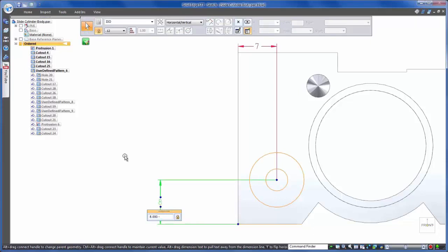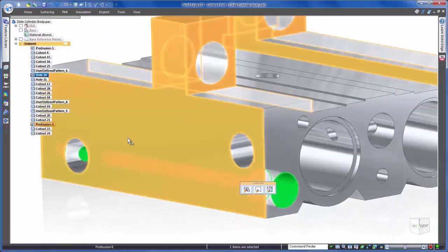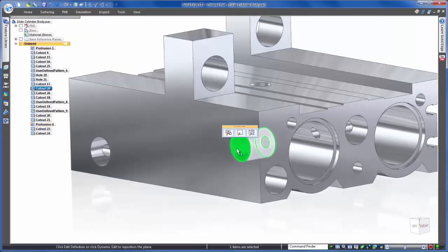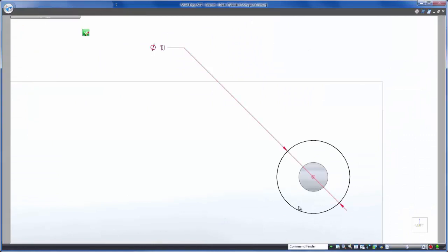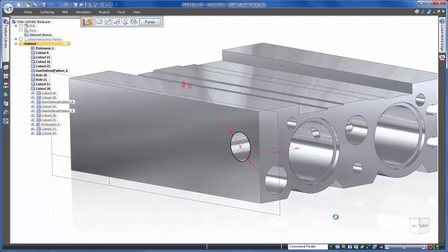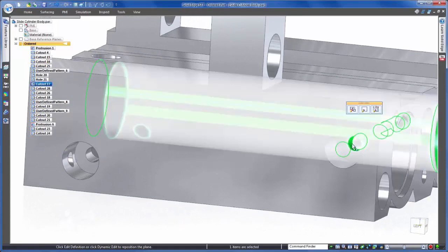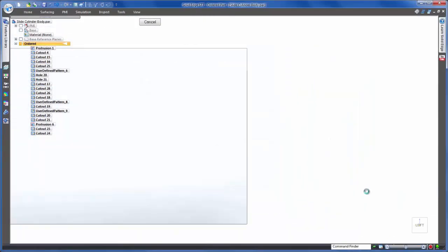Once again, by editing our profile, we can either key in exact values for dimensions or let Solid Edge do the calculation for us. Now that we've subtracted 1 millimeter to the front hole, we need to do the same with the top. Repeating the same steps, we notice that this hole is not defined the same way as the previous. This counterbore is modeled as a cut and is concentric to the smaller hole running through the slide cylinders.